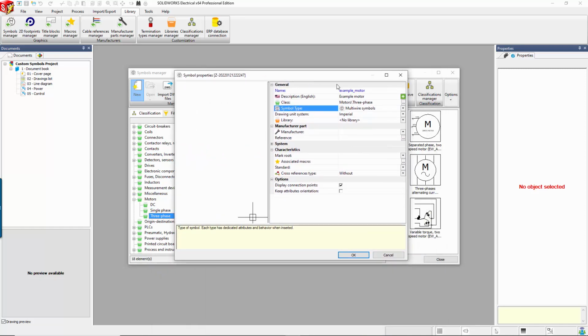They're usually what people are thinking about. There's a bunch of other examples for specific situations. A lot of these are kind of automation type symbols that come into play when you're creating an automatic terminal drawing or stuff like that. There's connection labels, a bunch of different label types. You have black boxes. The one that we're making today is a multi-wire schematic symbol, and that typically is used on a schematic sheet when you're doing point-to-point wiring.